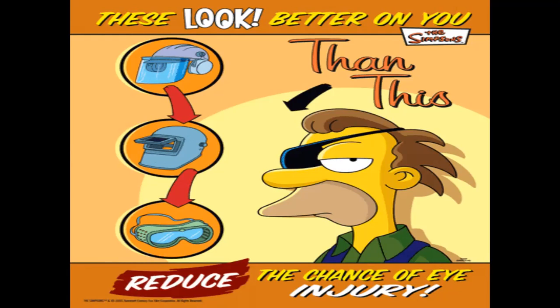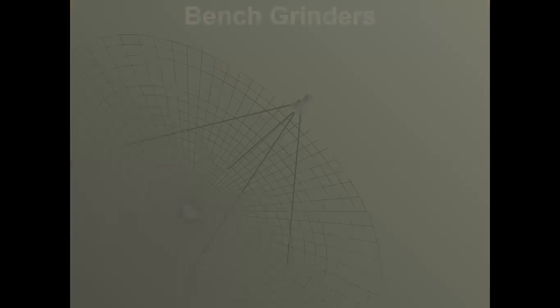We have a welding shield down here, and the front of that can be flipped up to do some grinding with. There is a clear plastic lens on the inside that is impact rated. And then below that, we have our safety goggles. Those are all ways of reducing eye injury. We always wear safety glasses anyways, but when working with something like a pedestal grinder where the chance of something pretty bad flying at us is present, that's when we definitely start to use those face shields.